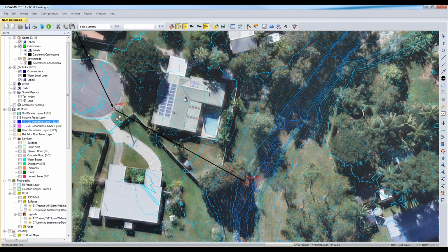So I'll draw an interface between. Just imagine there's a head wall down there. I'm drawing the interface layer, interface line, and that's to link the 1D to the 2D. That's correct. I'm linking the interface line to the 1D, and this is just putting the 1D flows into the 2D grid.